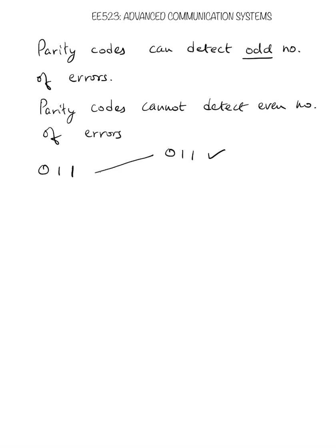Now let's introduce an error. Say in the first position, the first bit is 0, we make it 1. So the first bit has changed, and the second and third bits are correct. The receiver will check the parity and see if it has an even number of ones.